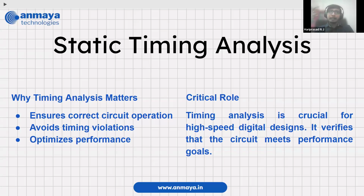So whenever I go for the timing analysis, one thing I have to do is avoid this metastability by appropriate methodologies. One is the analysis part, which we call static timing analysis. Dynamic timing analysis is also available, but this is static timing analysis, not dynamic timing analysis. Dynamic timing analysis usually uses simulation, where we see how it behaves.